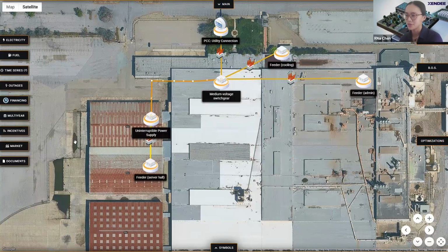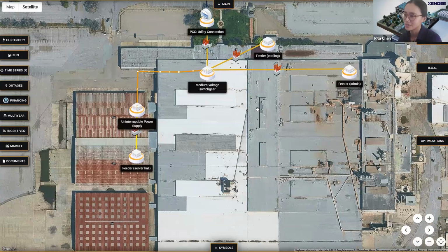Remember that in single node, we had aggregated all of our nodes into one singular load for our entire site. Now, for a lot of sites, or maybe just feasibility studies, it's totally okay to just aggregate all of your loads into the one site. But now that we have our connections for power flow included, we're going to separate our building loads into their respective locations. So I'm going to have two building loads in this case. I'm going to have my office/admin load, and then I'm going to have my actual load for the servers.